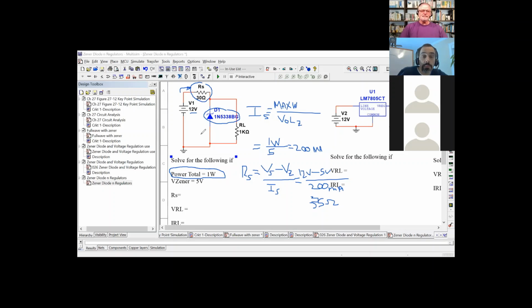So Charles, does the voltage on the Zener have to always be lower than the source voltage? No, your source voltage has to be higher than your Zener. Believe it or not, if it was equal, let's say our source voltage is 5 volts and our Zener is 5 volts. In all honesty, you won't get 5 volts out of that Zener because you're going to have a little bit of what they call wiggle room in that Zener. You may only get 4.5 volts out of it. That could affect your circuit. So always keep that in mind.